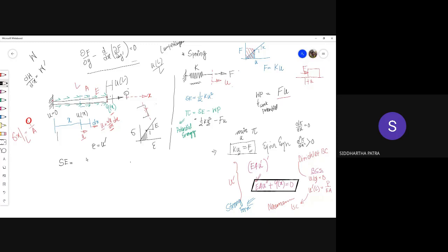Okay, and that is what you are supposed to get back when you release the bar. If, let's say, it is a vertical bar and you attach a weight, you would be able to pull it vertically and do this much amount of work on that weight. Okay, so how much is this? As you pointed out, that is sigma times epsilon, which is also actually sigma times epsilon by 2.